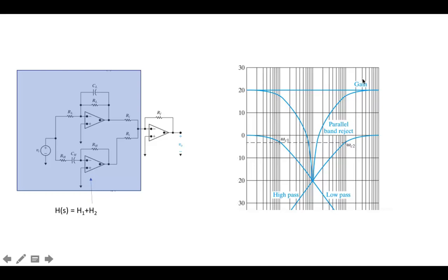The band reject filter, like the band pass filter, is technically designed to be a broadband band reject filter. If you want a very narrow band reject filter, like say you're rejecting 60 hertz, then that's a different sort of circuit, because this one is designed to work as a broadband. Once again, if these two curves, omega C1 and omega C2, get too close together, then out here in the passband region, you're not going to have quite the same behavior.